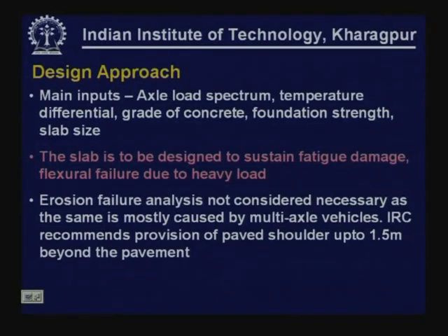So, the slab is to be designed to sustain fatigue damage and also flexural damage due to the application of heavy loads. Erosion failure, though, is considered important if we have multi-axle vehicles which produce higher deflections, but it is not very common that we see many multi-axle vehicles at present. IRC does not recommend any analysis for erosion, but it recommends provision of a paved shoulder up to 1.5 meters beyond the pavement to reduce erosion and pumping.